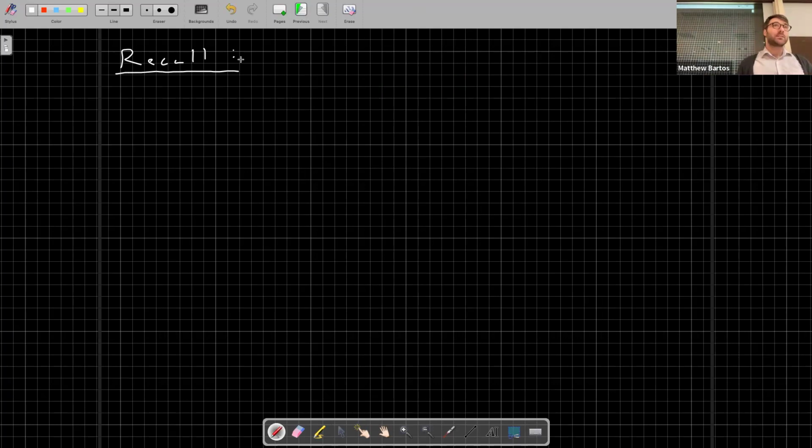So this came from basically coming up with two independent formulations for the mean shear stress in a pipe and then equating them. So the first expression for our mean shear stress comes from the definition of the friction slope. We had that the mean shear stress was equal to the acceleration due to gravity times the density times the hydraulic radius r times the friction slope. By the way, what is the hydraulic radius r defined as? Very good.